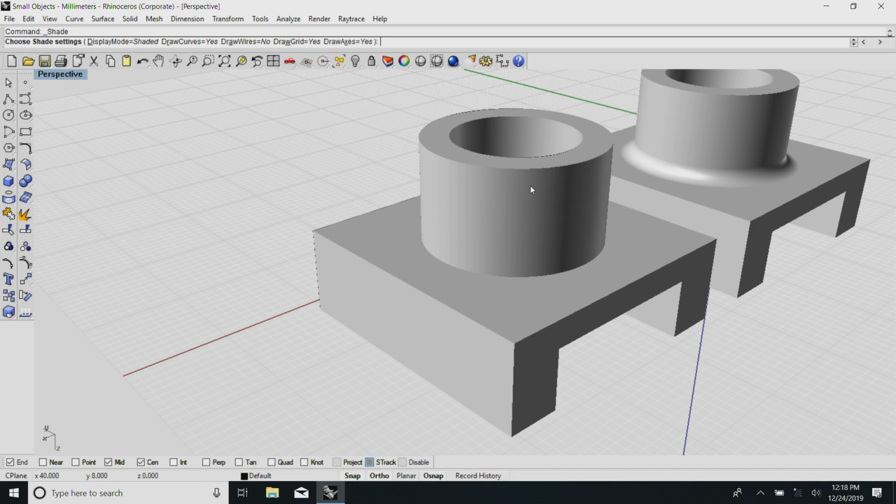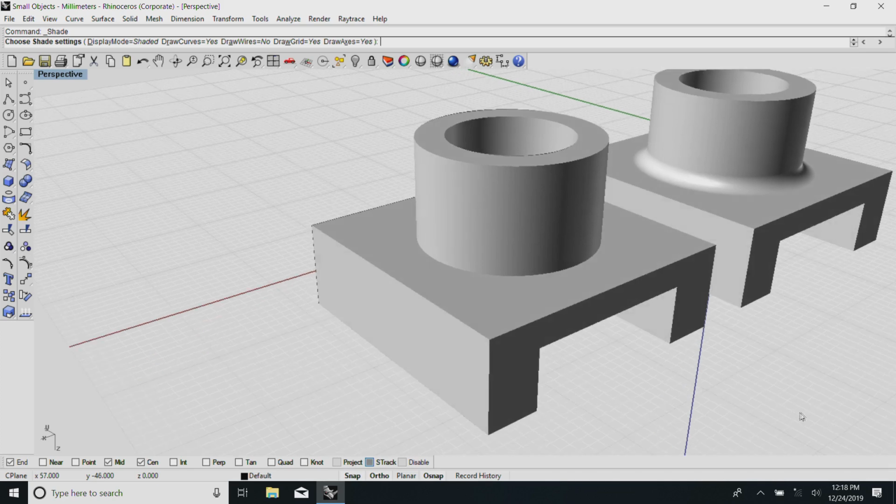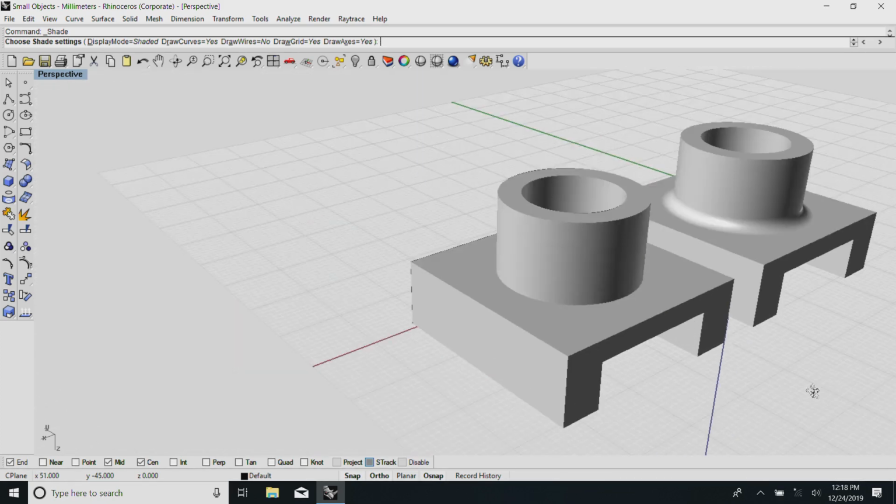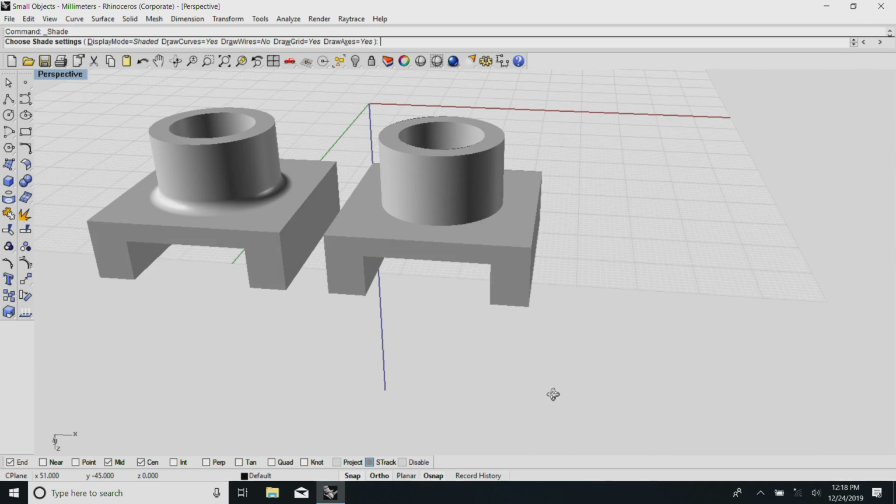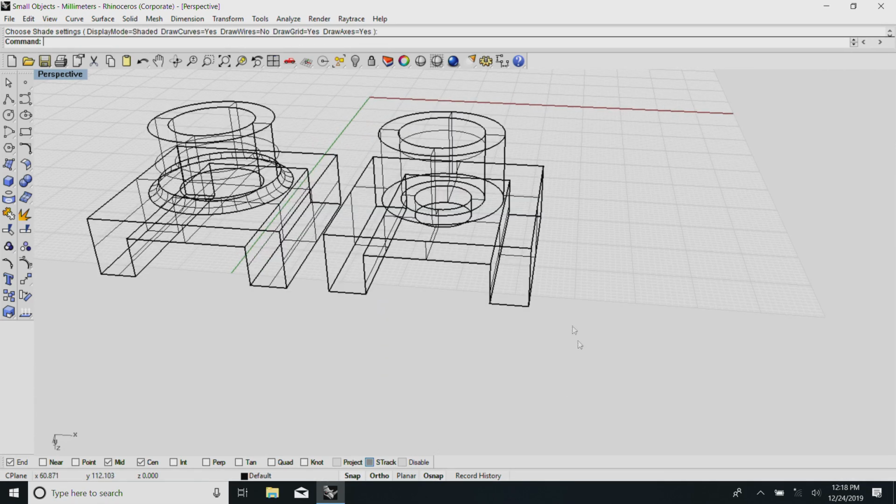They have first completed this turning operation by holding this flat in a four-jaw chuck and completed that, then held it inside and they have got it. You have seen this, both of them are exactly like what we are looking for.